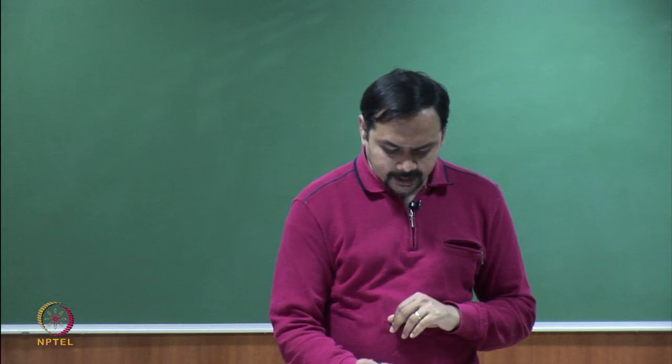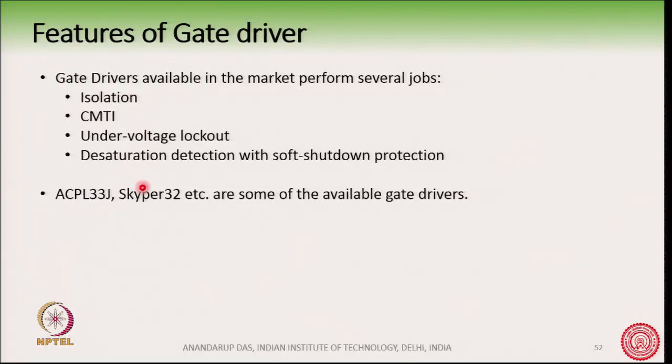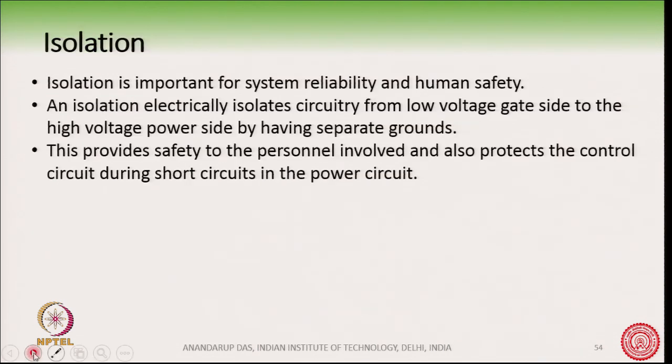There are 4 or 5 important terms. Apart from these, there are other important features in the gate driver, but isolation, CMTI, under voltage lockout, DSAT detection, these are some of the features of gate drivers.